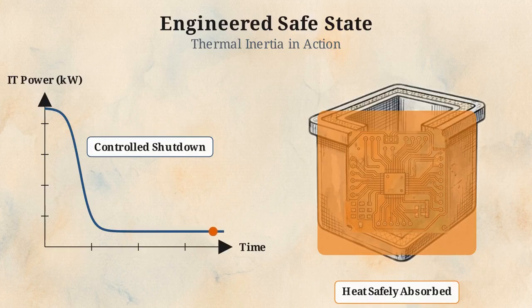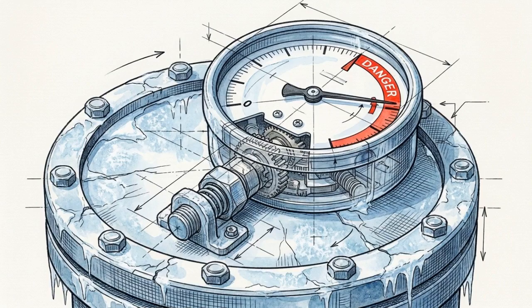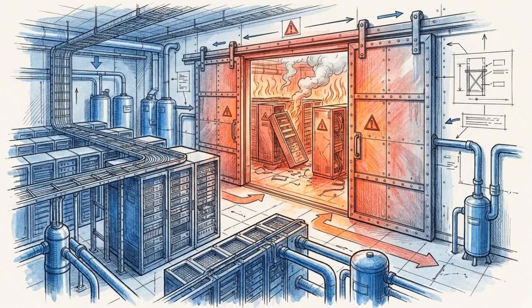In two-phase systems, failures like condenser fouling or the accumulation of non-condensable gases create dangerous, localized pressure spikes. These require immediate sensor detection and automated isolation to maintain the pressure boundary.